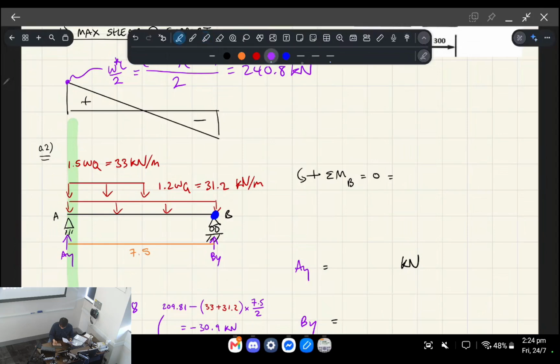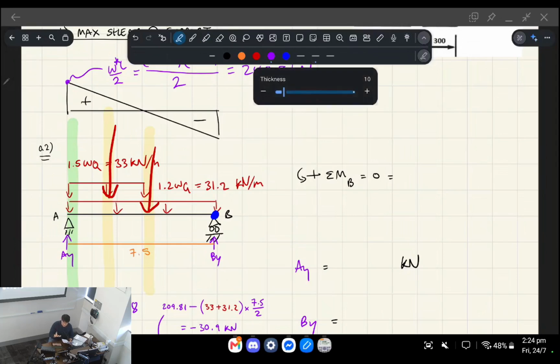And then we know that each of these distributed loads has an equivalent point load in those locations that you can see. Those will also have lines of action, which I'll do in yellow. So these are lines that go infinitely in both directions, like you can see there. What we're interested in is finding the perpendicular distance from our point B to those lines of action, okay? And that's called a lever arm, right?